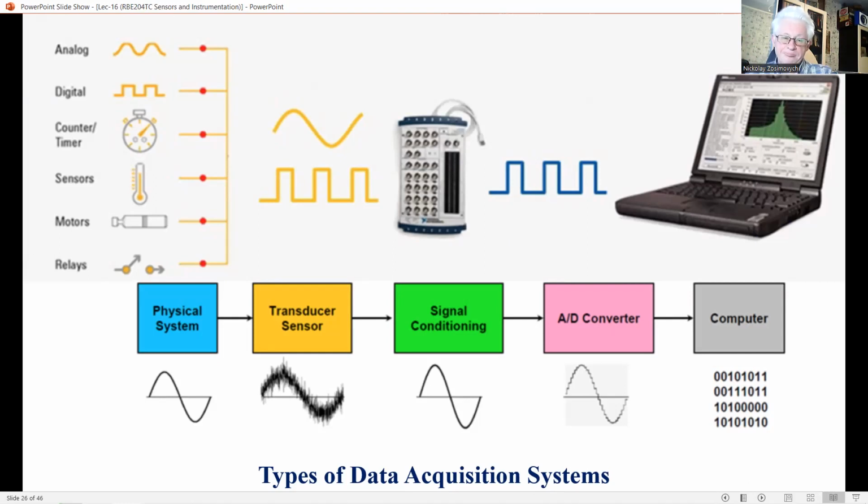Power supply. It may be needed for internal signal conditioning, and active sensors need power. DAQ power typically comes from the computer. And software. Driver software to operate our DAQ hardware for properly acquiring the sensing data. Application software for use by the computer to process the data for the end objective.